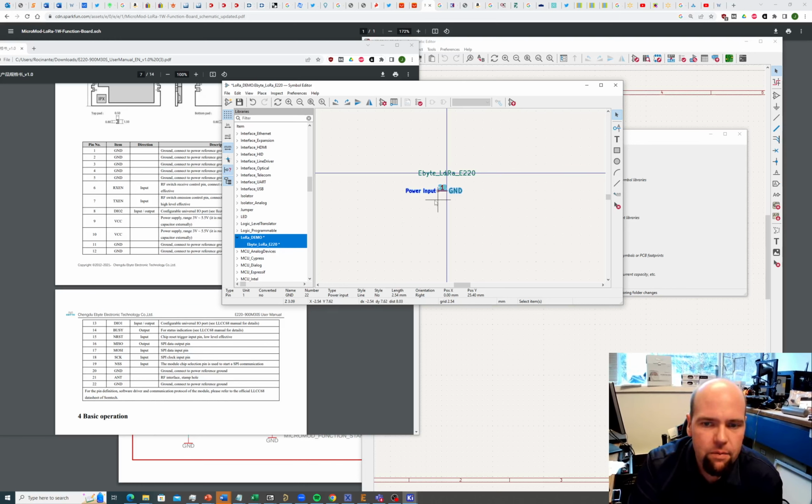Okay, we got a couple more pins to do. So I'm just going to go in pin order. So RX enable, TX enable. These are two pins on this radio, which has a power amplifier. So basically you need to determine, are you amplifying the signal coming in or amplifying the signal coming out? So you have to specify the directionality for the power amplifier. That's what these are, just digital signals specifying that.